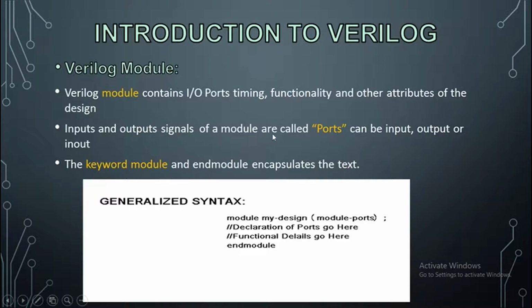The input and output signals of a module are called ports, and they can be inputs, outputs, and or bidirectional, which is inout. The module is closed with the keyword endmodule. Everything between module and endmodule will describe your logic.